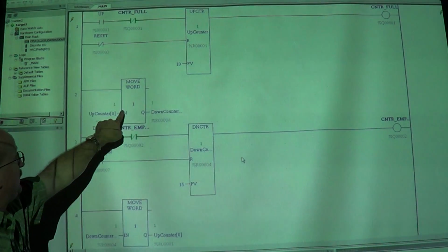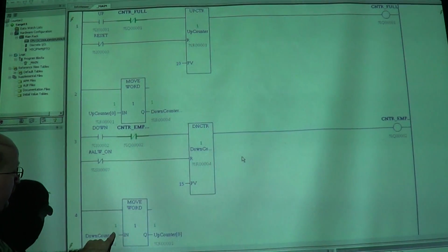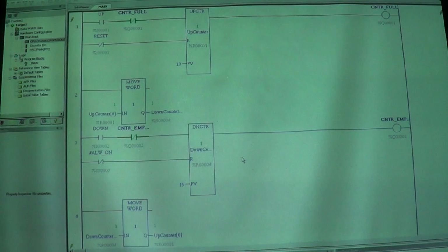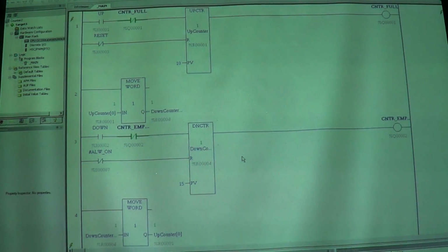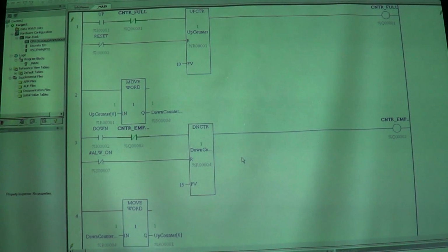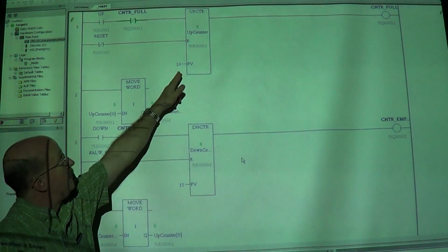My CV says 1, the CV there. My down counter says 1. Again, move word. You'll see ones all over the place because all of the CVs are now identical in both the up counter and the down counter. So I'll push a few more in there. Up, up, up, up. And you notice my down counter is tracking my up counter.